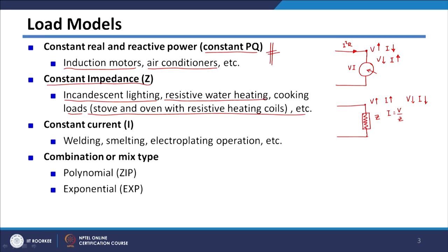So, when you are decreasing the voltage, you can see that current is decreasing. Whenever we keep a lower voltage here, your current is decreasing and you are getting less I square R loss in your distribution network, or in this feeder. Less amount of current is flowing in the feeder, that is why there is less I square R loss. This particular characteristic of this load is used in what is called CVR.